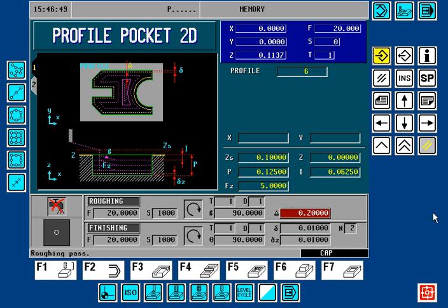I'm going to be using a 1/2 inch tool, so I'm going to use a 0.2 step over. Here we have a finish feed rate, finish RPM. We're using the same tool for rough and finish, and again the 90 degree entry into the part is a plunge. And I'm leaving 10 thousandths on the sidewall and 10 thousandths on the bottom as a finish pass. And here N is the number of sidewall passes for finish. So this will go 2 depth of cuts for the finish pass.